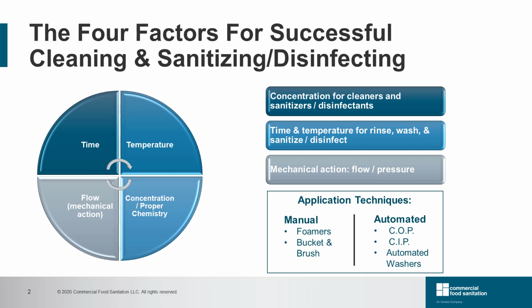For example, if the soil to be cleaned is greasy, we recommend using hot water and alkaline detergents for cleaning and using sufficient mechanical action during the cleaning process. If the concentration of the detergent is slightly lower than recommended, we may ensure proper cleaning by appropriately raising the water temperature and extending the scrubbing time.